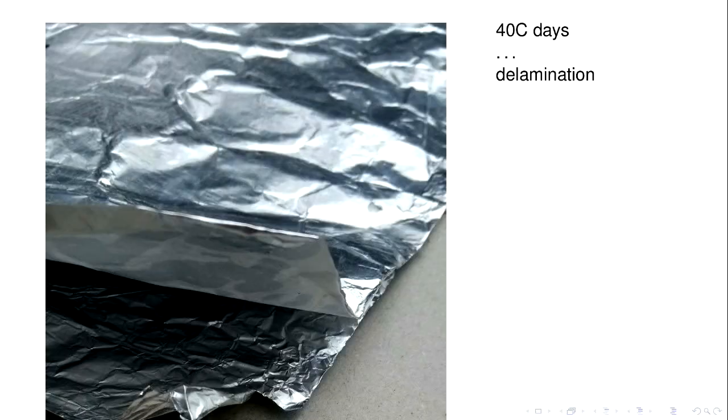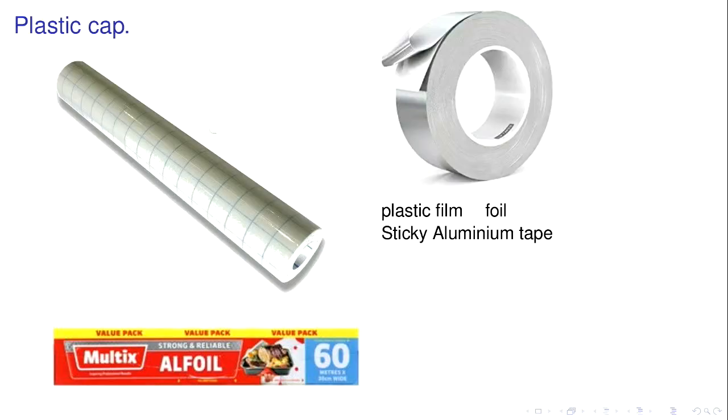So I thought, okay, if I can't do a wax paper capacitor that lasts, maybe I can do a plastic capacitor. So I pinched some book covering plastic, the type you use for kids' school books, and some more aluminium foil. And I had some sticky aluminium tape. My girls weren't very happy, but I pinched it from the craft box. And then what you do is you take yourself a piece of the book covering plastic. This particular one is 80 micron thick PVC. Sorry, no, polypropylene.